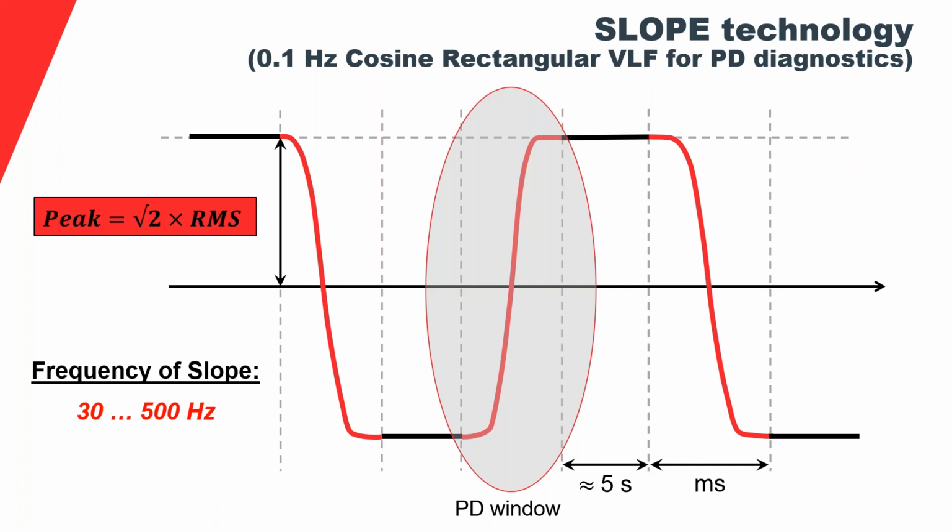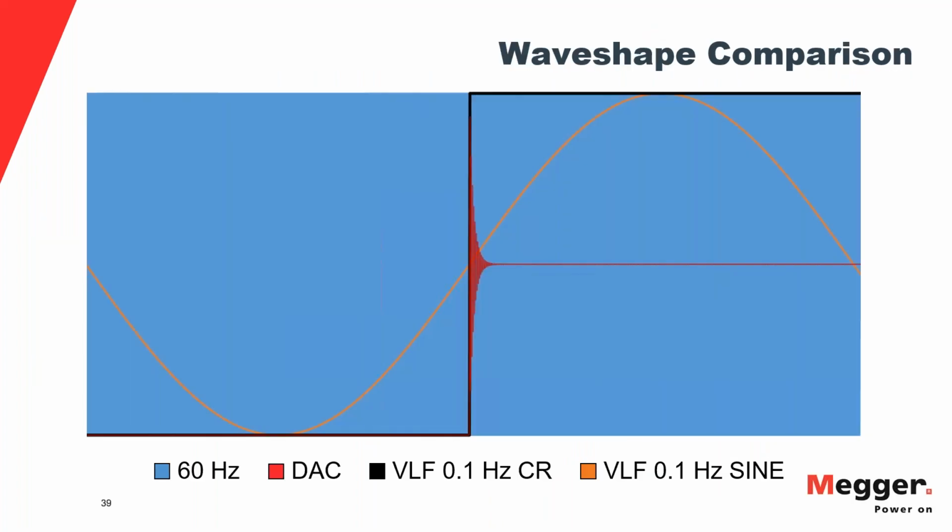And here I just plotted the waveforms to compare them, and I also included the sinusoidal. Remember, that was the second VLF waveform that was invented. And technically, from a diagnostics point of view, it's very straightforward. Just use damped AC for diagnostics testing and use slope if you want to do a monitored withstand.